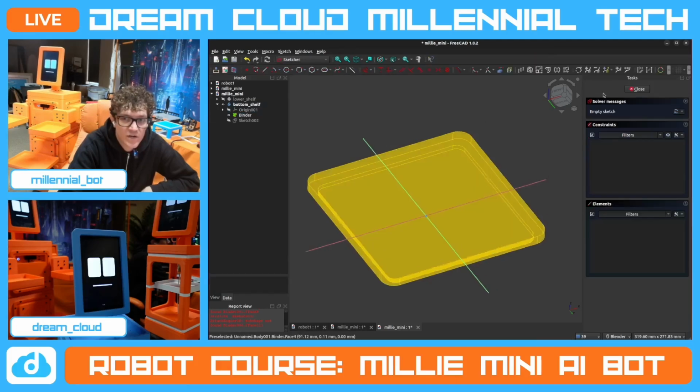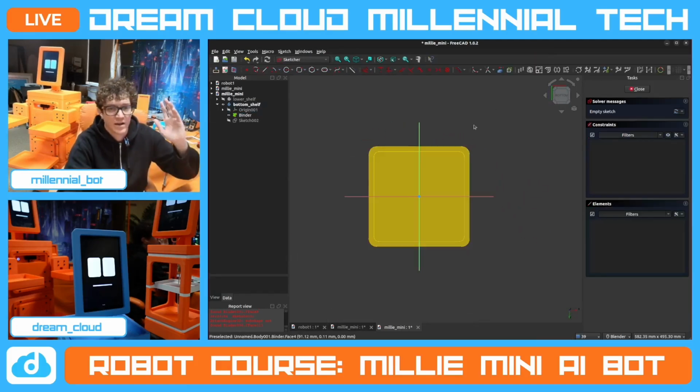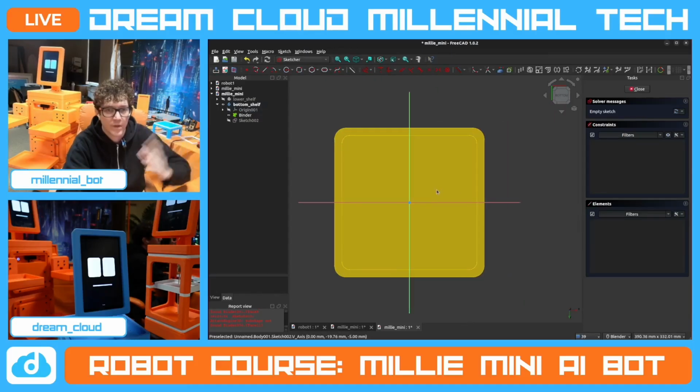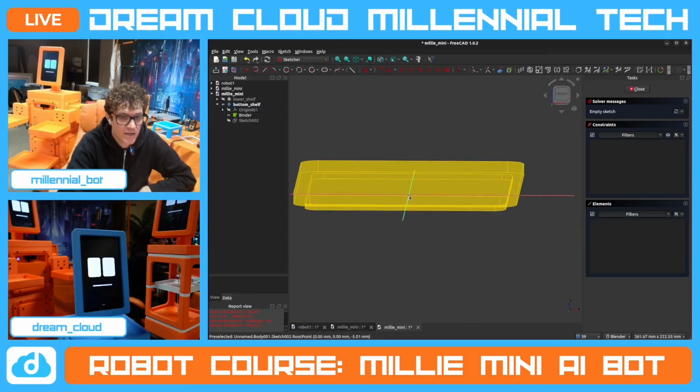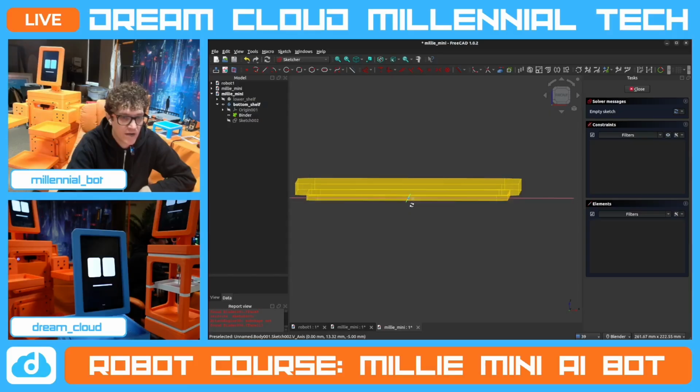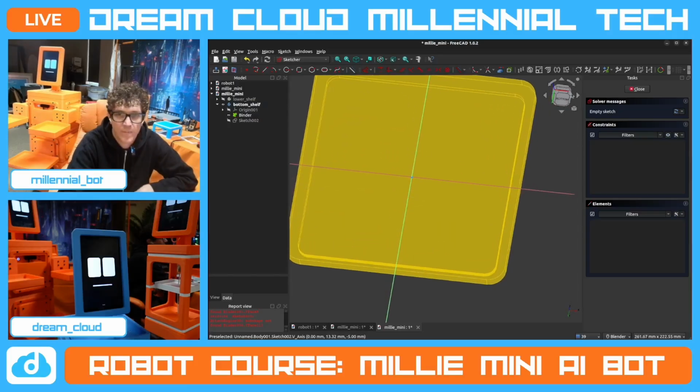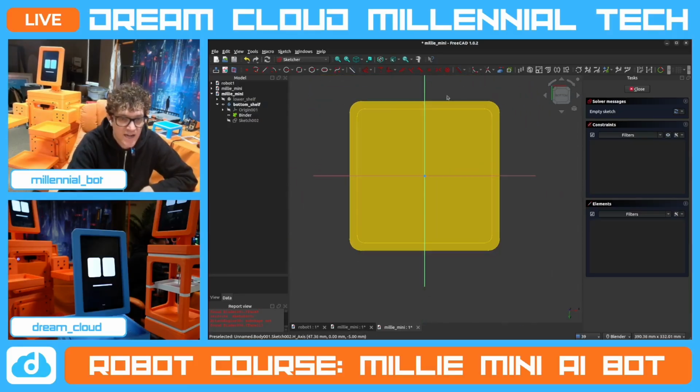And then all we have to do is create a sketch. Same thing, right? It opens this up, now we're drawing. We're on the XY plane, and you can see that that XY plane is on that surface, right? So that's all we did right now, we're just going to create a sketch on the bottom surface of this reference object, which is actually this object.